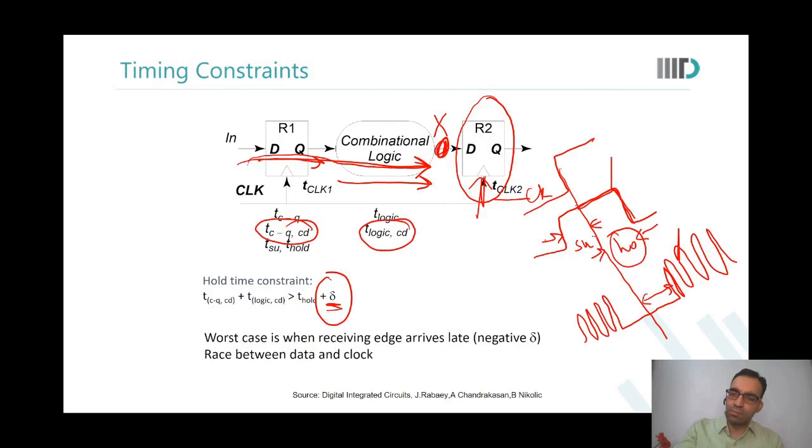Okay, right. I don't have to be concerned about the stable signal, just any change. You do not want any transition to happen. The first glitch should not arrive, which means that I have to look at the contamination delay.